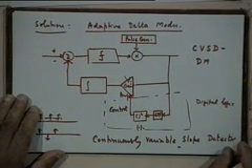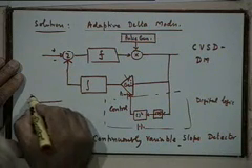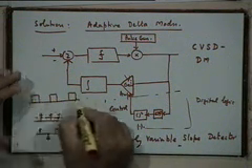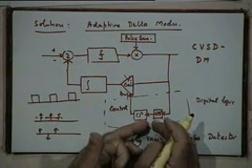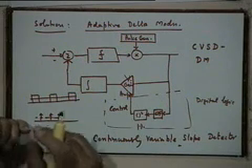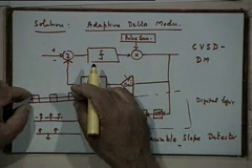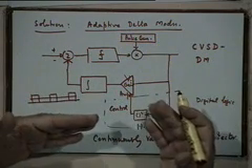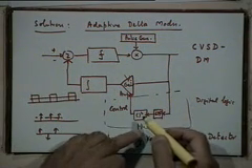So can you explain this one again, when are too many pulses detected? Yeah, because we get a large number of positive pulses, let's say 3 or 4 successive positive pulses. During that time interval, what does a low pass filter do? It basically carries out some kind of averaging operation over some time interval. If you look at the impulse response of a low pass filter and at that convolution operation, essentially it is an averaging operation over a short interval of time. If a few positive pulses come, it will produce an output which is the average of these values. I am just roughly describing the effect of the low pass filter. The precise action will be governed by the precise nature of the low pass filter.